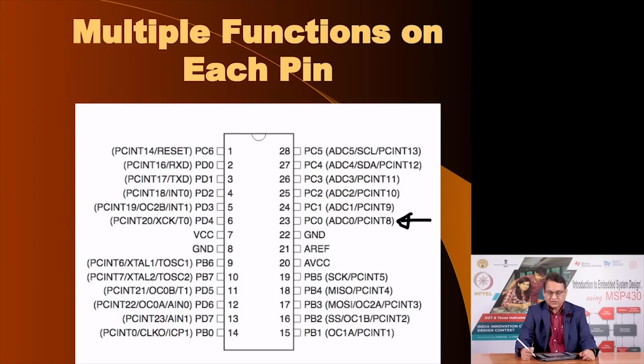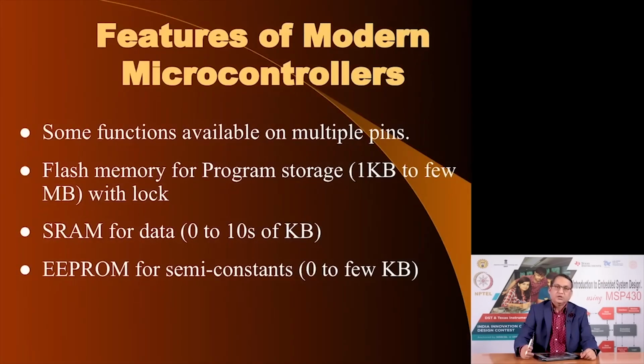and therefore you may either have to compromise by finding some other pin which has similar functionality, or if you were to use more recent, more advanced microcontrollers, you would find that in such microcontrollers a given function may be available not only on one pin, it may be available on multiple pins, and so you can judiciously use a function on a different pin so that you can continue to use the other function on that pin that you wanted to use.